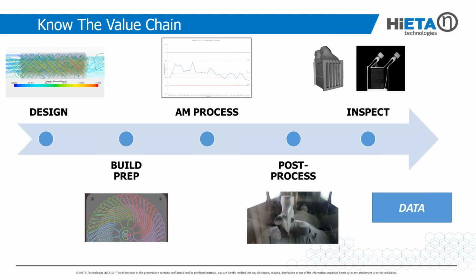After that, it helps us in processing and inspection: we can see if there is a problem and identify the problem's place and time. We then have post-processing, obviously powder removal and thermal stress release. We have inspections, and then we save the data and manage it afterwards.